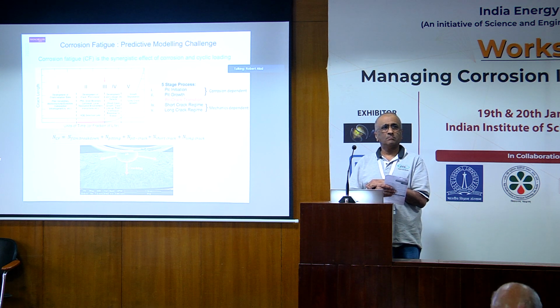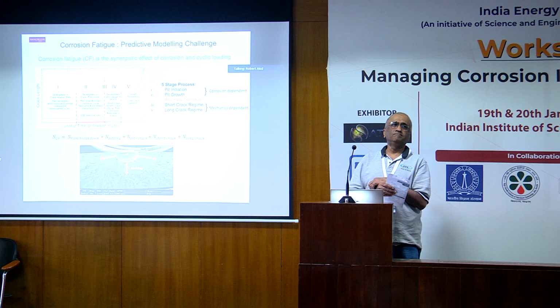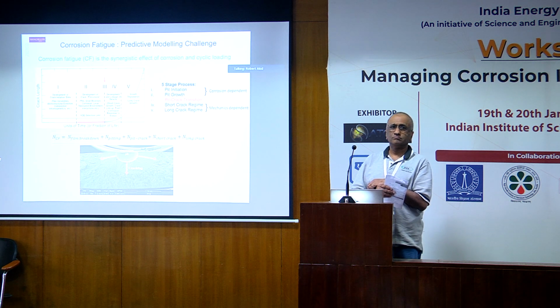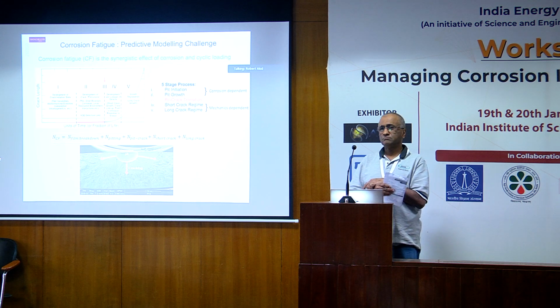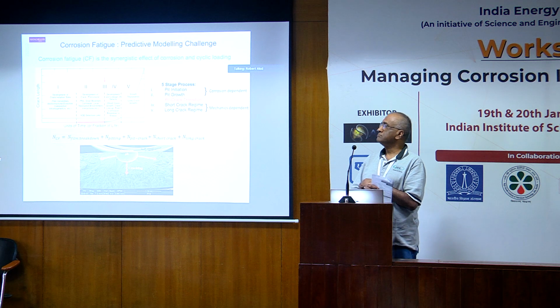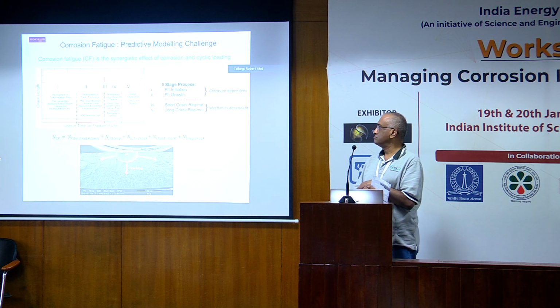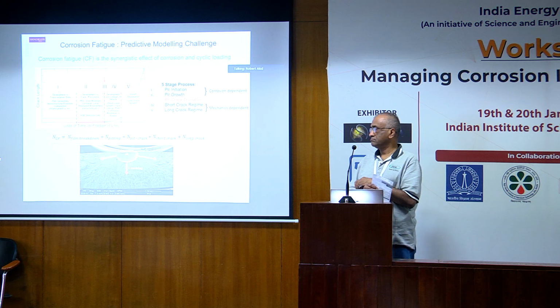What our next stage is, and we do actually include this in the model, is that corrosion is always taking place, but if the crack growth is faster than the pit growth, then we get continued cracking. If the pit growth is faster than the cracking, then it subsumes the crack itself, and it delays the onset of cracking.